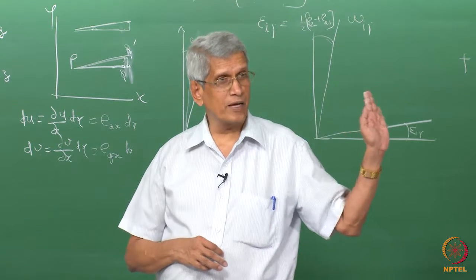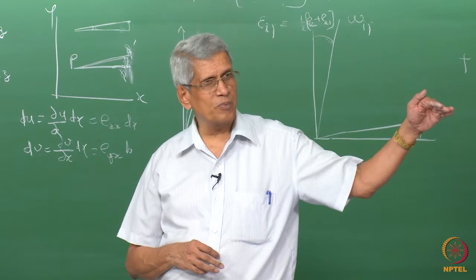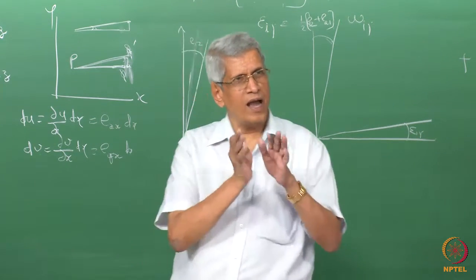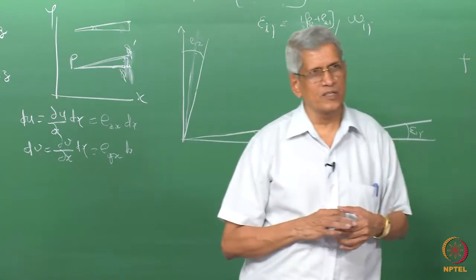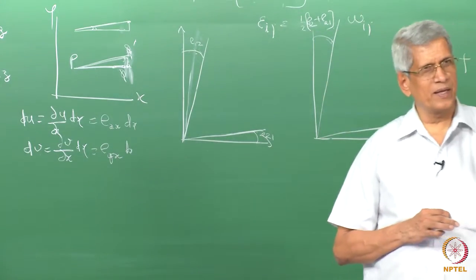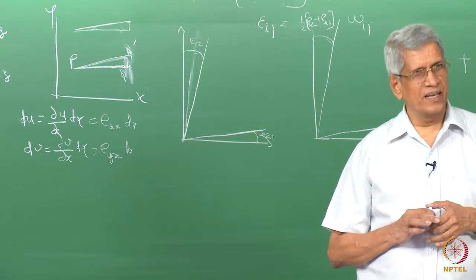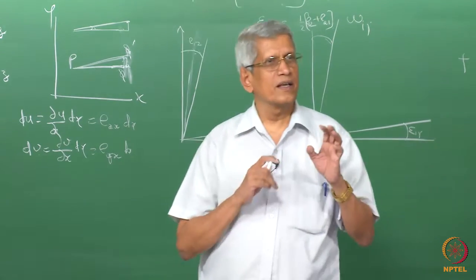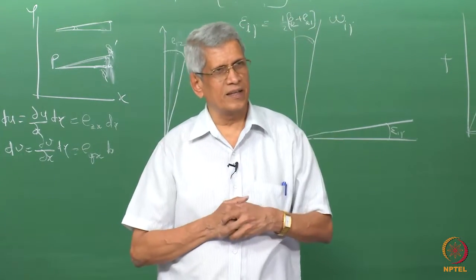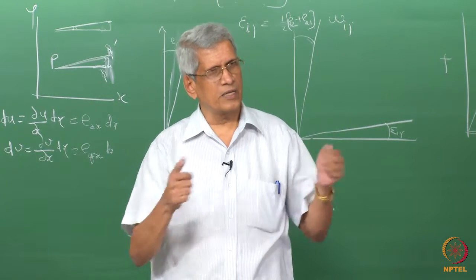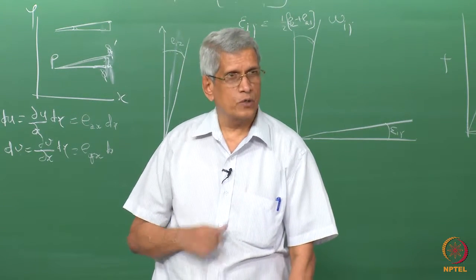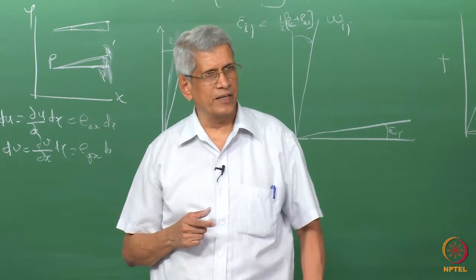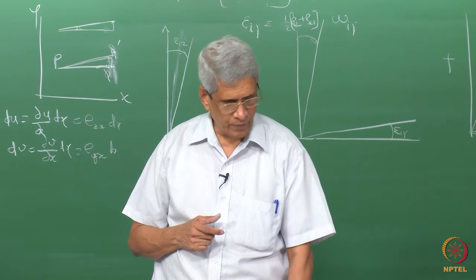The axis may not be exactly, now here the axes are at 45 degrees with respect to it. There may be some other rotation which may have to be given. Essentially, at some angle with respect to a coordinate system which we have chosen, we can apply just simple dilatation and we get the same. That dilatation will be one tension in one direction and compression in the other direction, okay. So in the case of a square here, what is going to happen is that it will be exactly 45 degrees, okay.